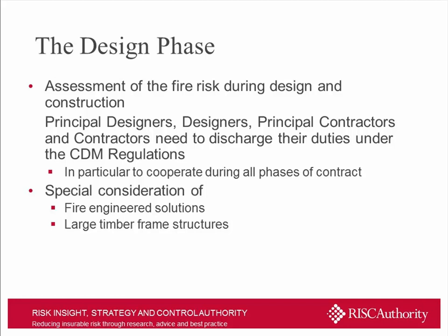But the design phase within the Joint Code does require an assessment of fire risk. So some thought needs to go into the potential for fire and what's going to be done, or what can be done by way of scheduling the materials that might ensure that risk is minimised. And it involves the principal designers and contractors, a requirement for them to discharge their duties under the CDM regs, and in particular to cooperate during all phases. Now, that's easier said than done very often. But the requirement exists, and there's an opportunity there if we're involved in a project at an early enough stage to try and ensure that some of these issues are picked up upon.